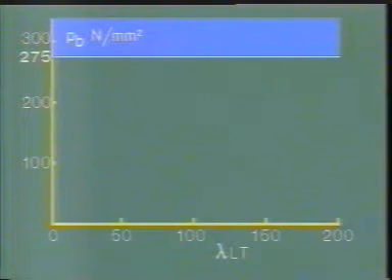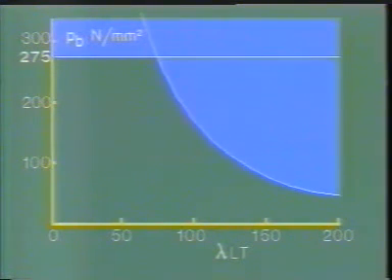In terms of extreme fibre stress, this behaviour plots as a line which has a very low value when the slenderness is high, but has a very high value when the slenderness is low. This line too is an upper bound to the actual bending strength. For low slenderness material, strength is the limiting condition.